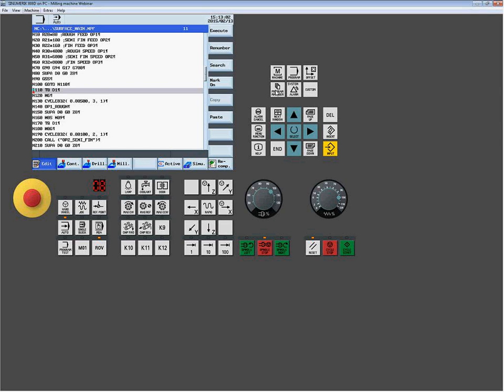Then tool change. Now you see, I like to put this D1. This is what offset I want to load. You don't have to. Earlier we saw they were using the D command because the system will automatically load based on that command if the parameters are set up that way. That was why we actually had the problem we did with the prefetching, because this machine is set up to load tools on the T code, but once you put another T code in, it supersedes the last.